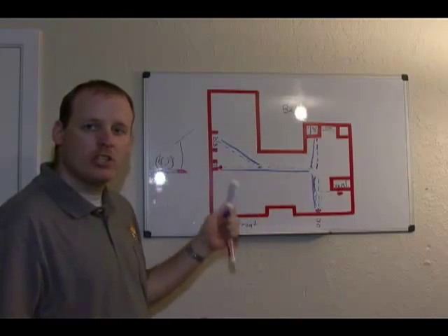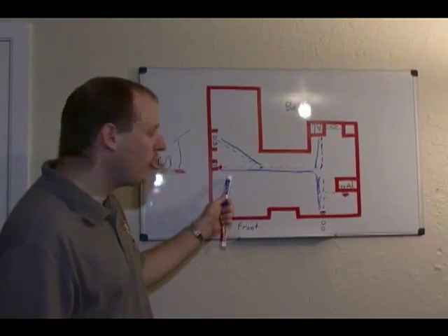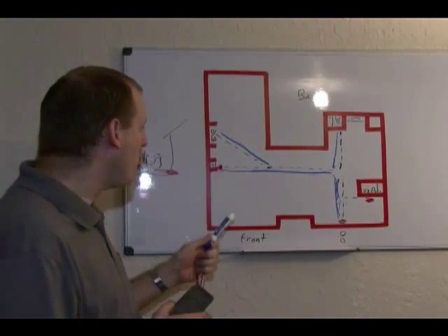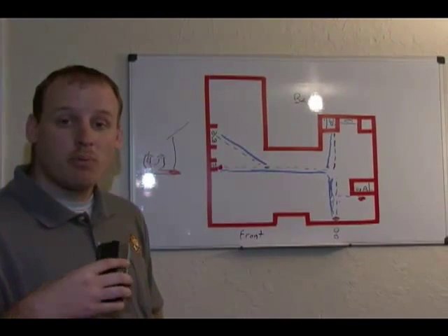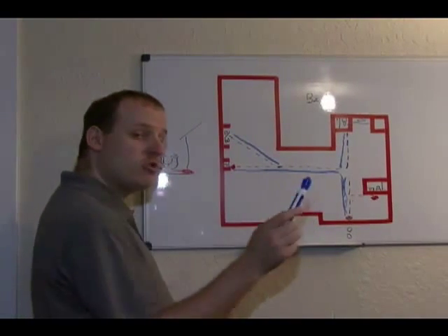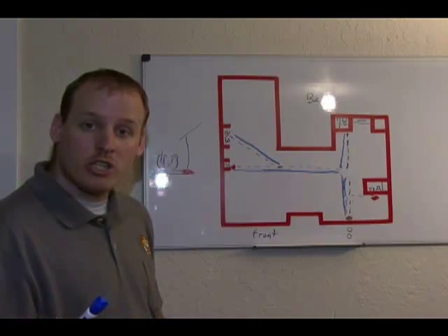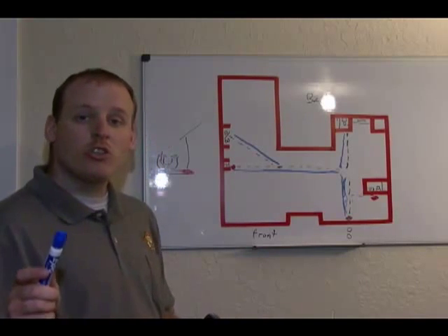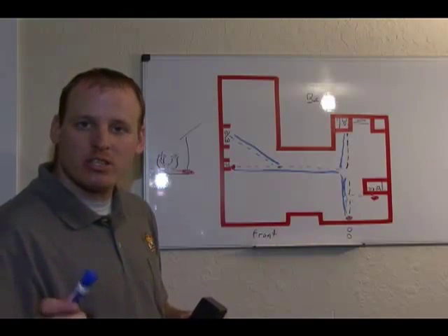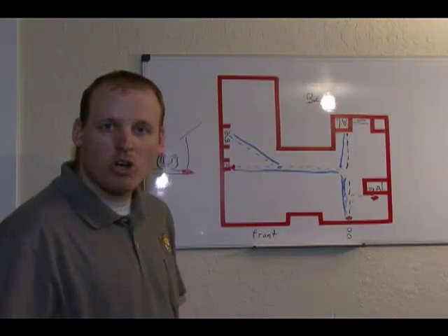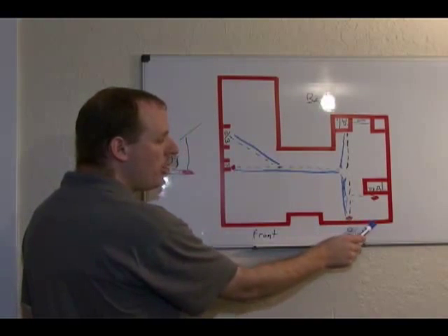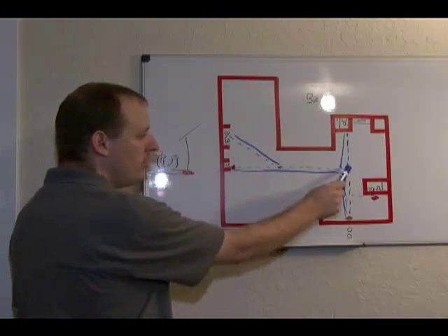All we really care about is whether it is leaking or not. The only way to determine that is to fill it up with water. That is a very, very important note. What we actually do in our leak locations is use rubber inflatable test balls with air hoses attached to them, but we also use a camera to assist us in putting the test balls where we want them to be. We can use the camera to know where we need to put our test balls in the line.